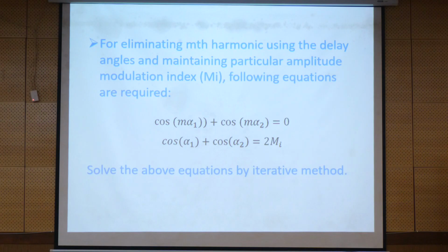If you go beyond a modulation index greater than 1, it becomes over modulation. In most cases they won't go for over modulation, because the output is going to be distorted. We will have good control over the modulation index between 0 and 1. We will talk about the modulation index more later, but it is one of the parameters to maintain the linear region of your circuit.